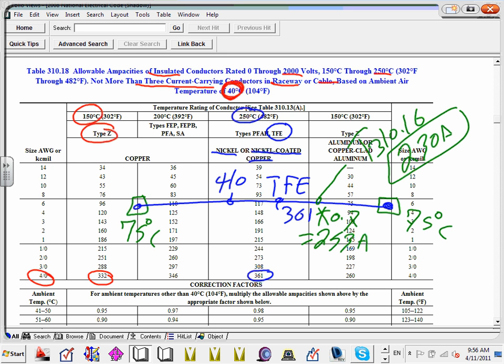Can you guys see that? So the question would be, Camille, who cares about all this calculation? Why should I use it if I'm already governed by this? It allows you to put conductors in a very hot environment, derate them, and still come up with a really good ampacity. You don't have to oversize them hugely because of the insulation. If you do the same calculation based on THHN, you're going to find that it carries a very small amount of current.